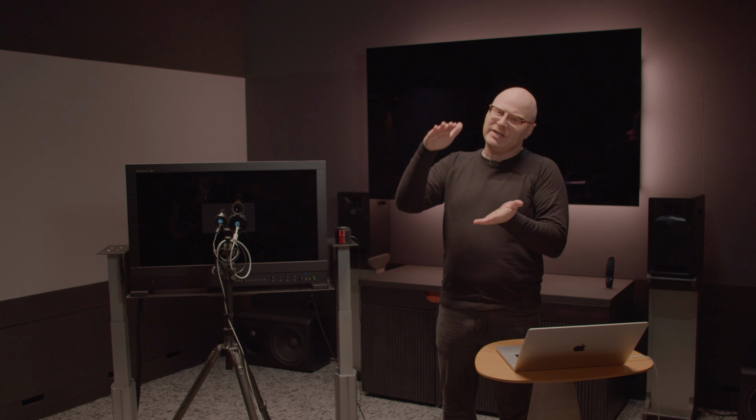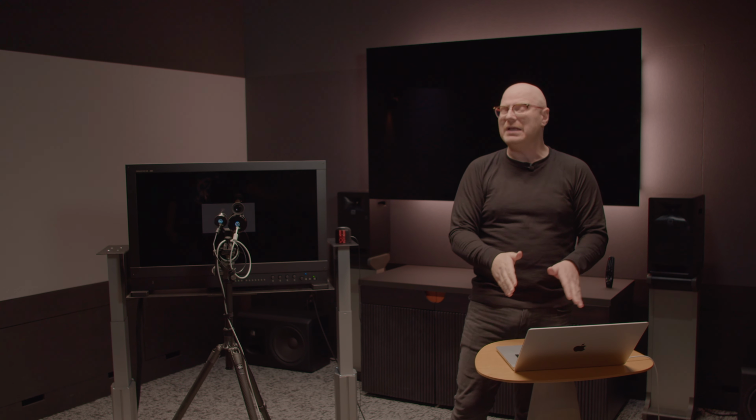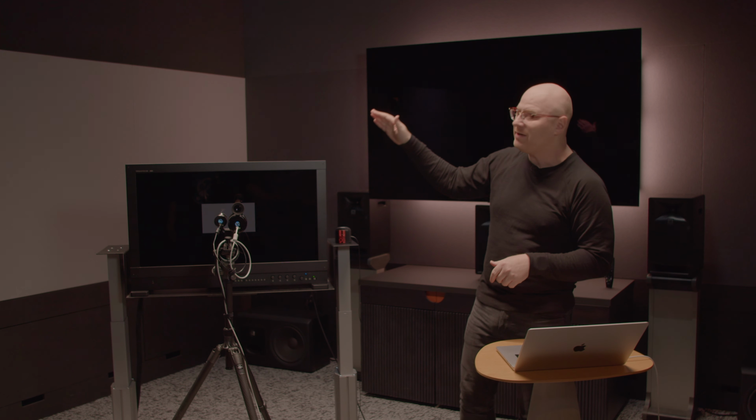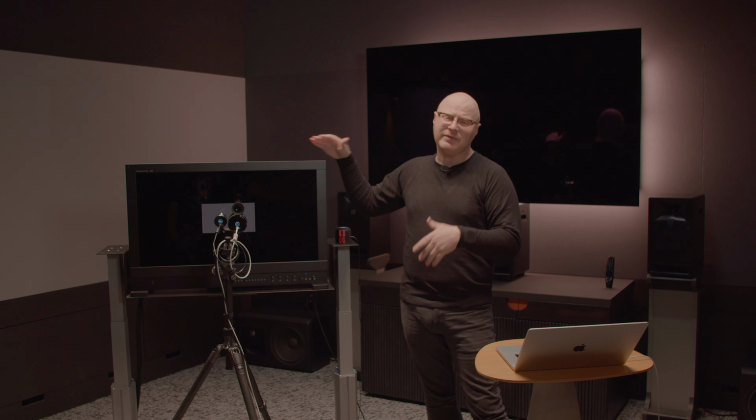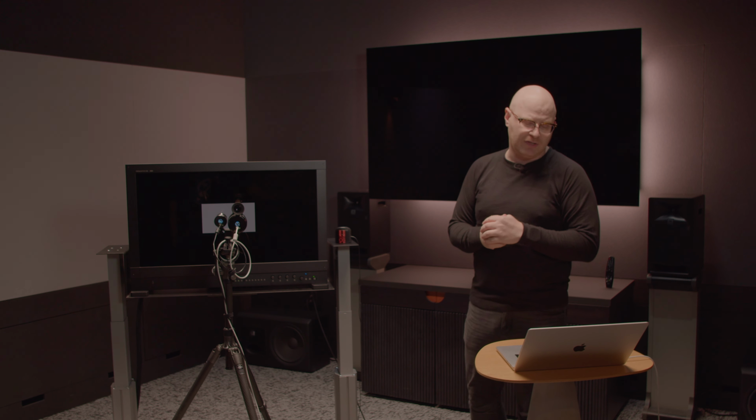If you have a monitor such as the Sony BVM-HX310 with a lot of hours on it, especially in dynamic range mode, the wear and tear is going to start to bring down that luminance. Doesn't mean it's not going to calibrate well. It just means that you might not be able to hit that peak luminance like you're able to. We've certainly seen some of these hit 1,000 plus nits, and we've seen some of them hit 960, 980, even a little lower depending on their age and their use.